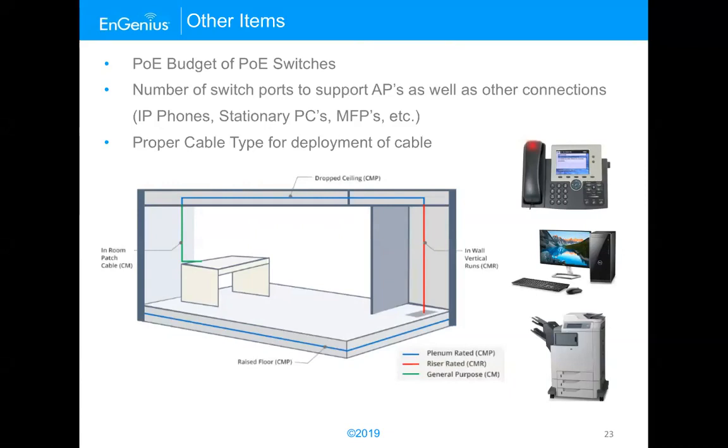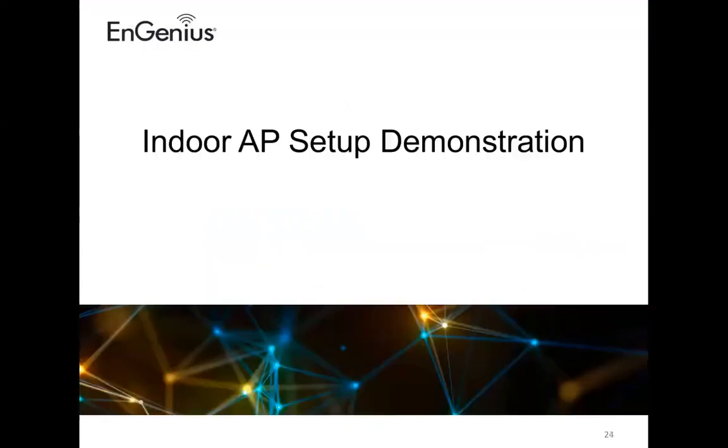Obviously, you want to make sure you're using the right cable so you actually get the best experience. For example, this in-wall cable, labeled CMR, would be solid cable. For the patch cable, the CM, general purpose cable, that would be mostly a stranded cable if I'm not powering anything off of that. Those are two different cable types, and I'll use them for two different reasons. It's important to grab the right cable, not only for indoors but outdoors as well.